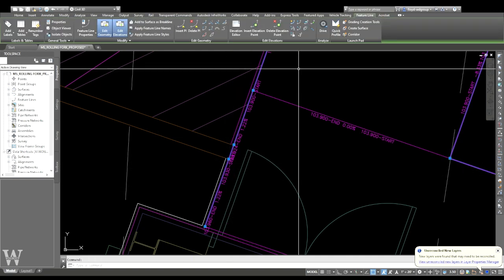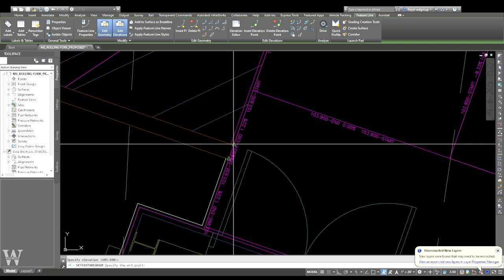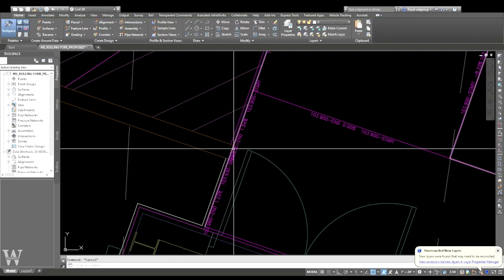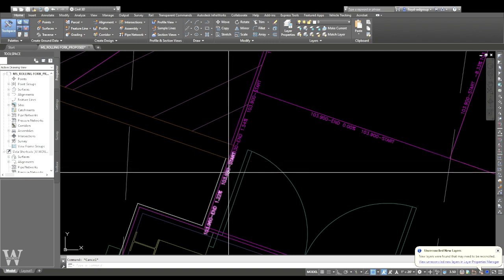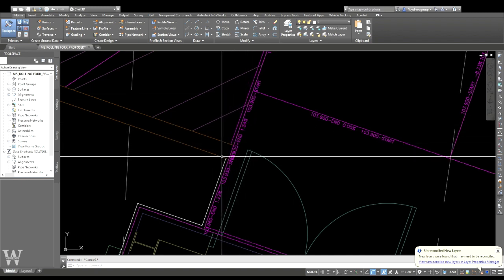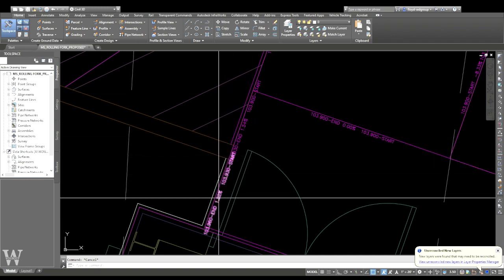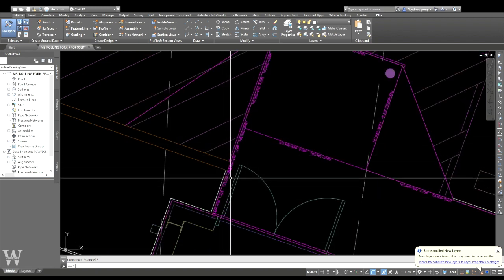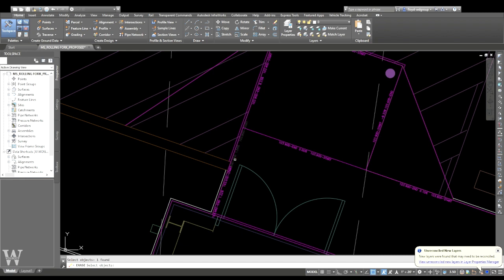And then I'm going to slope from here to here and grade 0, because I've got to set my curve right here. But I can't slope, I can't do what I was going to do. I was going to make that curve 103.90, but it's too steep right here and it doesn't meet ADA, and my client wants this to be ADA access right there.